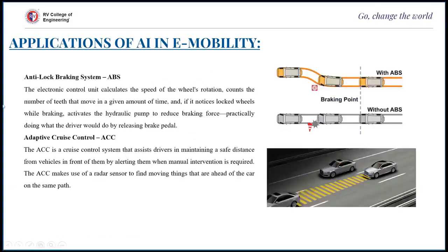Let's talk about ABS, anti-lock braking system. It is the electronic control system of the vehicle that keeps the wheels from locking up. That is, it prevents the locking up of wheels. There is an encoder, that is, it consists of a transducer and a phonic wheel which is located on each wheel. They are made up of a gear wheel that rotates with the vehicle's wheel.